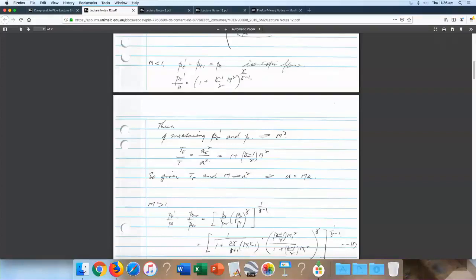So I could draw my control volume. So here's my rocket, and I can draw a control volume that is arbitrarily large, but I have an AE where the pressure is something, and the rest of it, A minus AE, is atmospheric pressure, assumed.